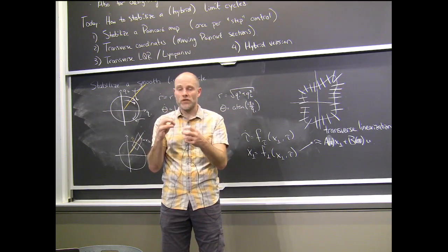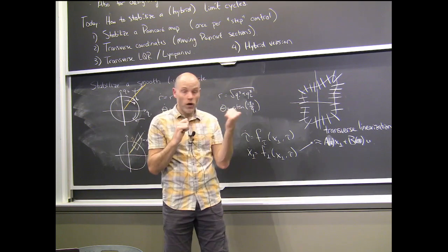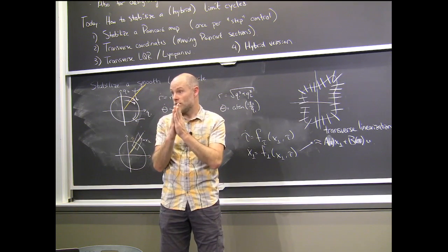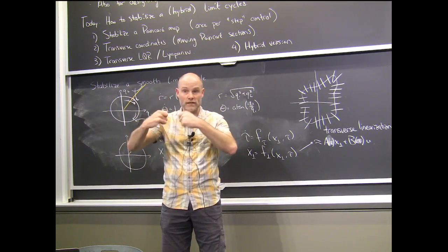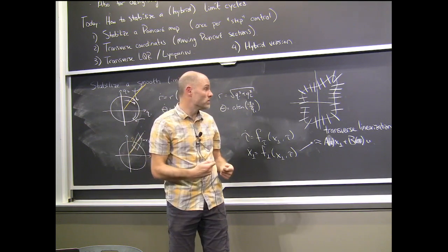The natural thing for most of these periodic systems is to not try to be stable along the orbit. LQR on the transverse coordinates is a very natural way to do that. It's not the only way to do that. You could hide it in a more complicated objective that you're solving with RL or anything. Those lessons still hold, right?